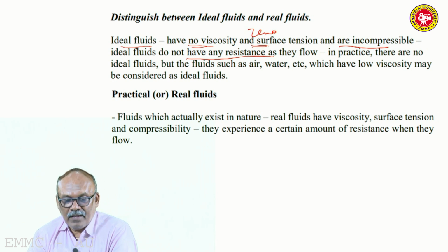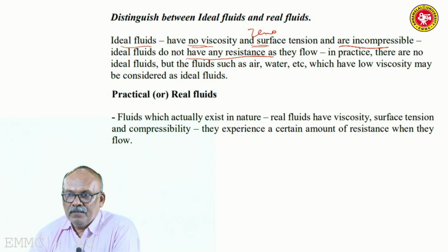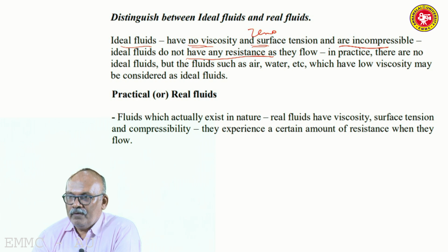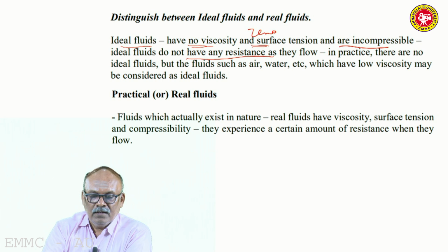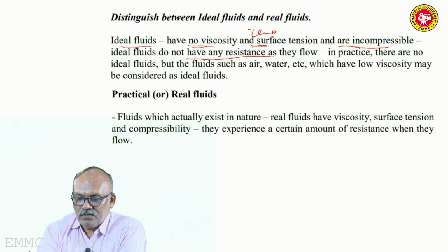That is, we said that if you assume the fluid particles to move in layers, the fluid particles in one layer will offer resistance to the movement of fluid molecules in the other layer, right? So they offer shearing resistance. So in case of ideal fluids, they do not have any resistance as they flow.